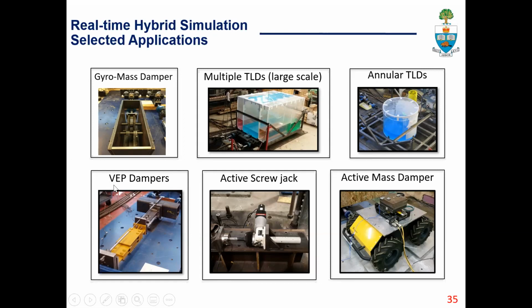The viscoelastic flux damper that is shown on the bottom left is a study in collaboration with Professor Christopoulos from University of Toronto. One of Professor Christopoulos's students developed a design methodology called P-spectra, and working together with them, we have performed single degree and multi-degree of freedom real-time hybrid simulations, around 200 real-time hybrid simulations to verify that design methodology.